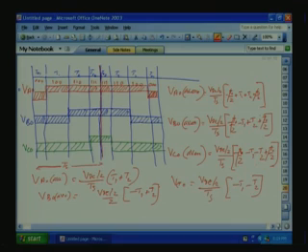Now what we have to do? T1, T2 in a sector we have found out. For a general angle alpha, that you substitute and we can find out VS0, VB0, VC0 average for alpha varies from 0 to 60 degree, how the variation happens. Then we can also find out how it happens for other sectors, and if you know the average variation for 60 degree, we can repeat it for other sectors, because it is circular, the average variation is tracing a circular space vector. That means the phase voltage average variation is sinusoidal. So 0 to 60 is sufficient.